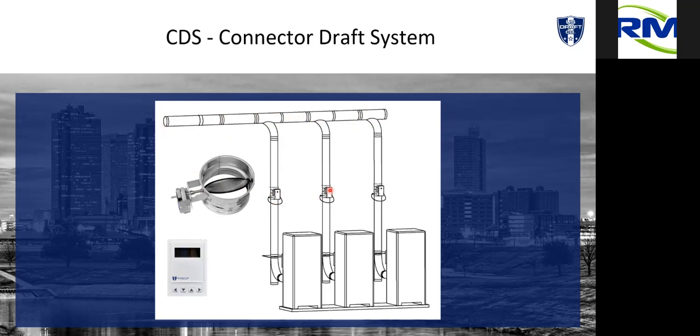This is really critical, or really advantageous when you get. I think of a job in Chicago where they had 3 Category 4 boilers and 4 Category 2 water heaters. So the water heaters wanted to be running at about 1/10 of an inch negative, and the boilers wanted to run at about 2/10 of an inch positive. There's no way you could do that naturally without CDSs. So we actually ran the fan for the entire system, set the dampers for each appliance for whatever they wanted, and then every boiler got exactly what it wanted at the time.